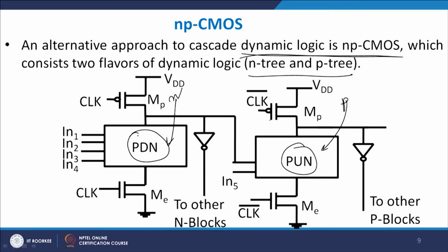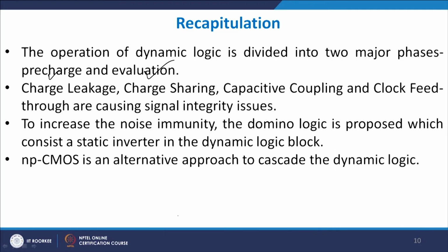With these definitions understood, let me recapitulate what we have learned in dynamic logic. Till today, we have finished off our understanding of dynamic fully combinational logic. From next time onwards we will start with sequential as well as logical effort. As I discussed with you, dynamic logic is divided into two phases, one known as pre-charge, another known as evaluation. Pre-charge is when the clock is low and your PMOS switches on, and therefore the output node is charged by VDD to 1.